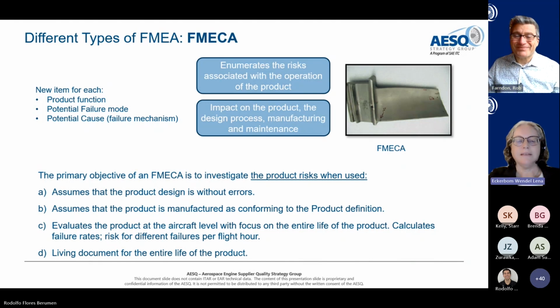Yeah. And this is a requirement for the type certificate holder to be able to assess the numbers of different types of product failures. But for a design responsible supplier, can you do an FMECA? Yes, you can. With sufficient information from a customer or the design accountable person or organization, you can have enough knowledge to assess your product and what the contributions of your product would be into your customer's total risk assessment at system level.